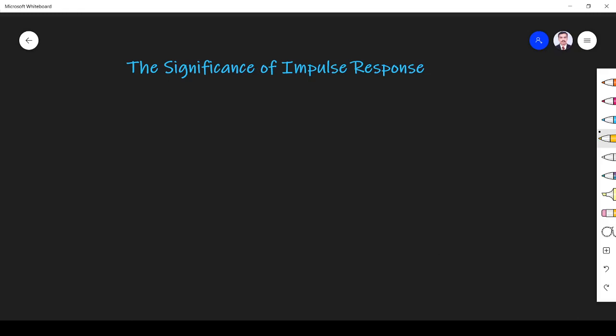In this video, we see why we need impulse response, how it is related to frequency response and translation. I will explain with one example that will help you understand the importance of learning these parameters. First, let us take one system defined by the equation y of n is equal to x of n plus x of n minus 1. I want to find the impulse response.